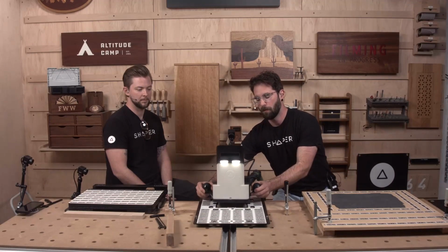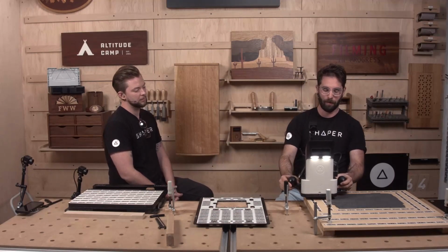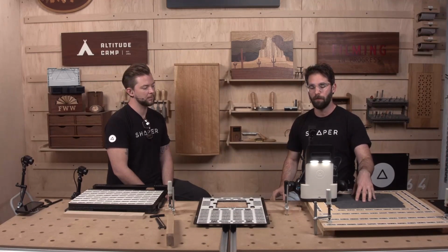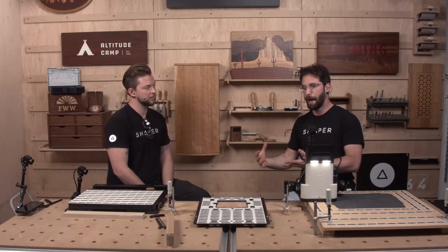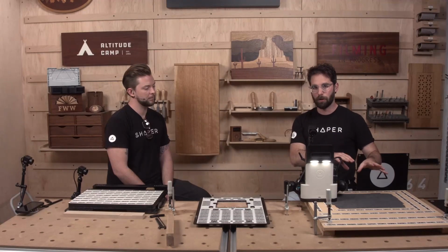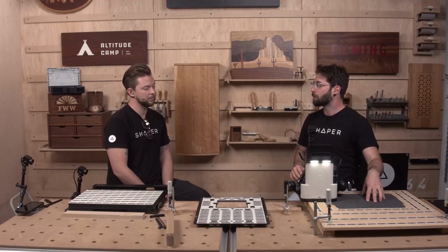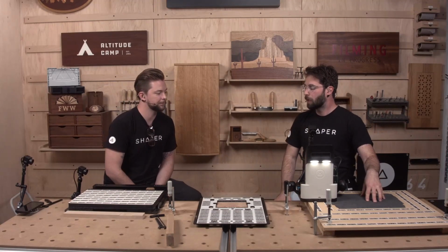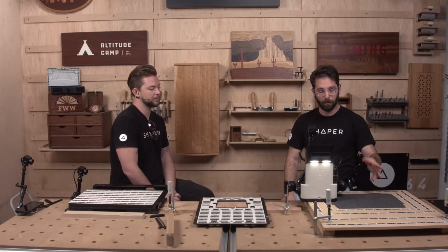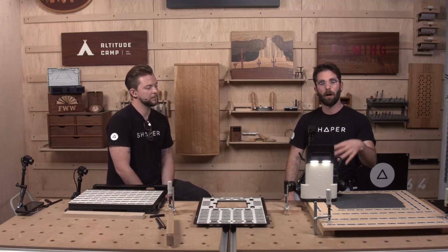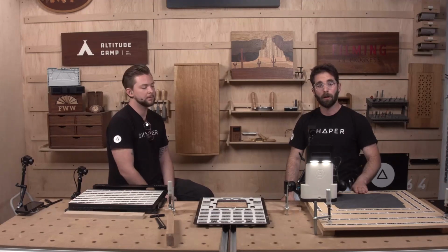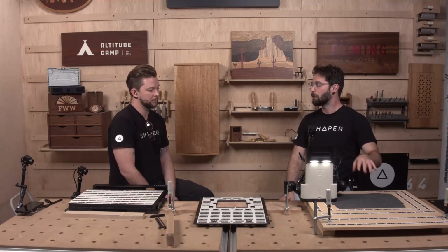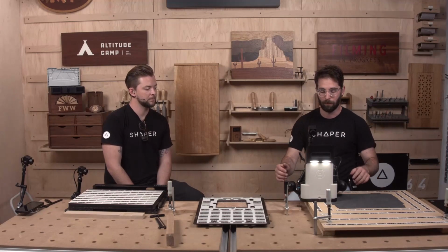Now, there are a few cases where in the past you might have had a tricky time touching off on the work surface itself. What we've recommended in the past is that you move your Origin off of, typically it's a soft surface, right? Soft woods, foams, whatever it may be. Soft surface where you have those problems, we would recommend that you move Origin off of that soft surface onto a hard surface where you can do that Z-Touch. But now with manual Z-Touch, you'll be able to touch off on these soft surfaces directly.